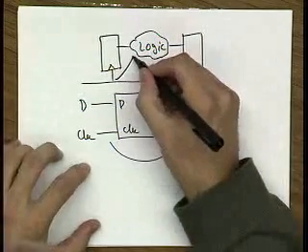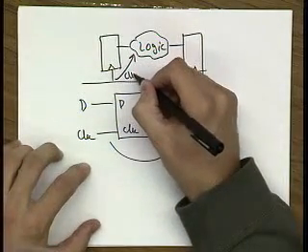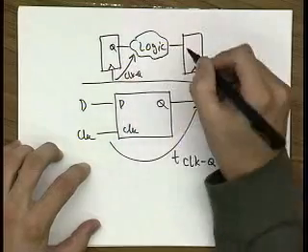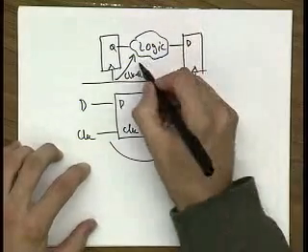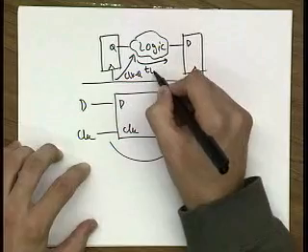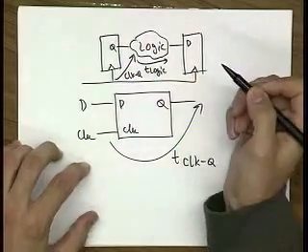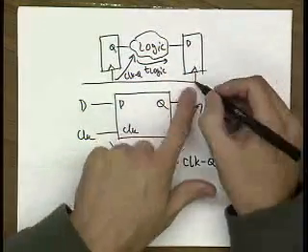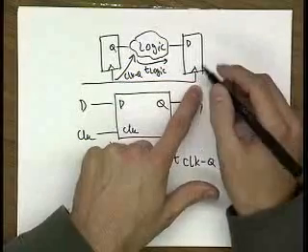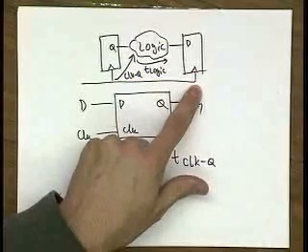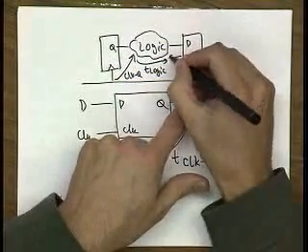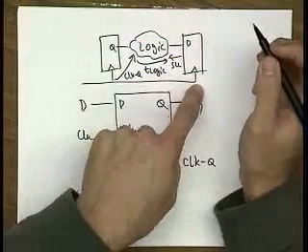So you have the clock-to-Q of this design, then from there you have logic delay. Before you get the edge of this clock, which is basically the next cycle, you have to bring the data in at least a setup time before.